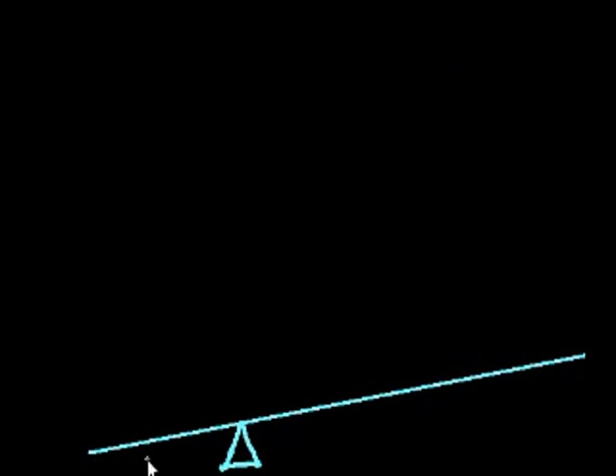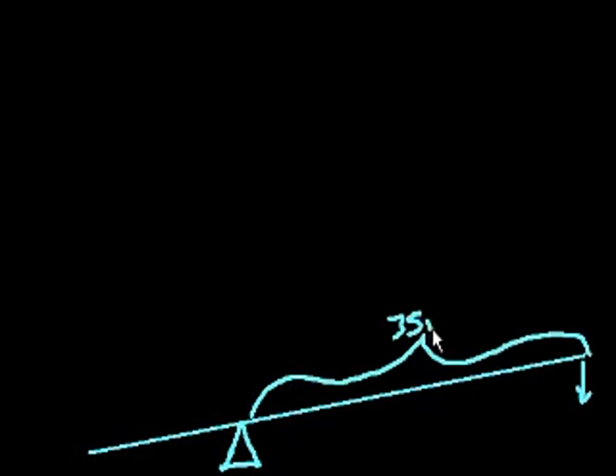So let's say that I'm going to push up here. Well, no, let me see what I want to do. I want to push down here with a force of, let's say that this distance right here is 35 meters. This distance is 5 meters. And let's say I'm going to push down with a force of 7 newtons. And what I want to figure out is how heavy of an object can I lift here?